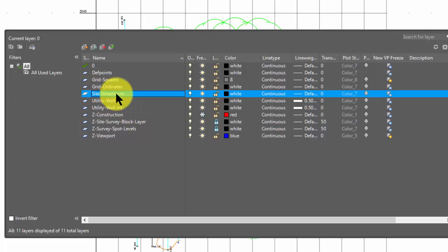Right, I'm going to change the site dimensions one a bit. I'm going to press home, select that, and cut, Control X, put a hyphen there, and then do a Control V, get rid of that space, and I've got dimension site now. So I press enter, and in fact I want to modify that a bit further. So F2, I'll put another hyphen there, and I'm going to put in MS for model space, and I'm going to make another layer based on this one,